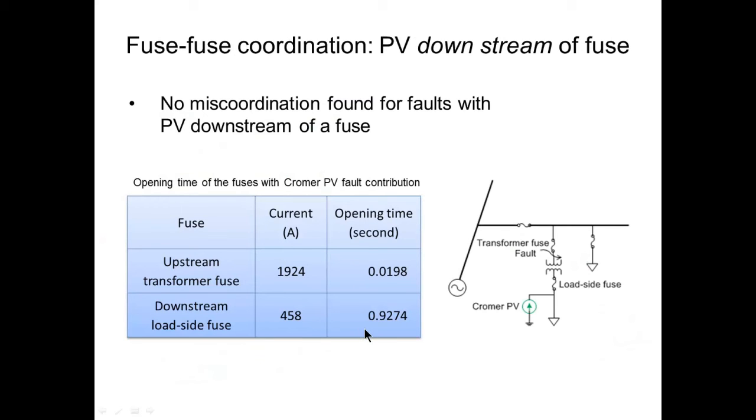The opening time, again calculated by MATLAB for the given TCC curves, is 0.9 seconds. That is well above the 0.02 seconds under which the lateral fuse operates. Therefore, the load side fuse does not blow, maintaining coordination.